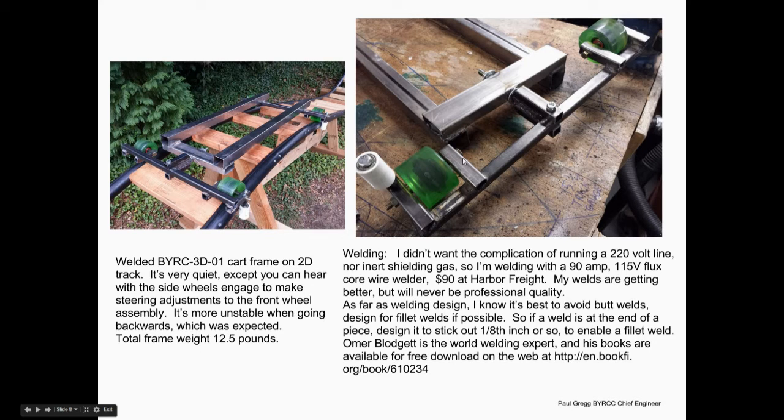For instance, you can see these welds. Instead of just butt welding the frame together in the corners, which would result in a fairly small joint area, I run these lower frames 1/8 of an inch past this cross frame, and then put a fillet weld in there. And then I did the same thing here. I stick this out 1/8 of an inch, do a fillet weld on the bottom. So I've got an inch and a half, 3 inches, 4, 5 inches of weld holding that joint together, instead of just an inch and a half or something if I'd butt welded it.